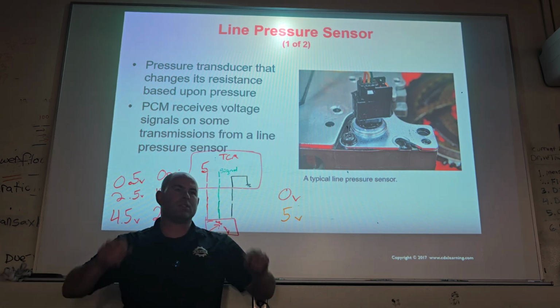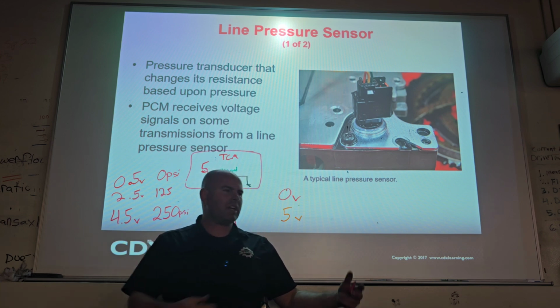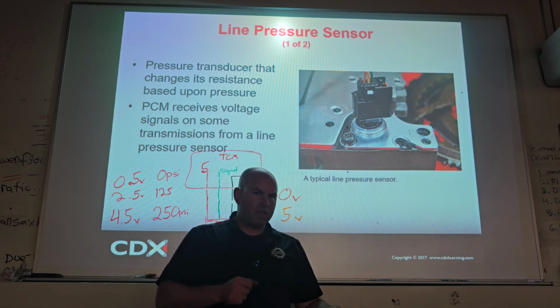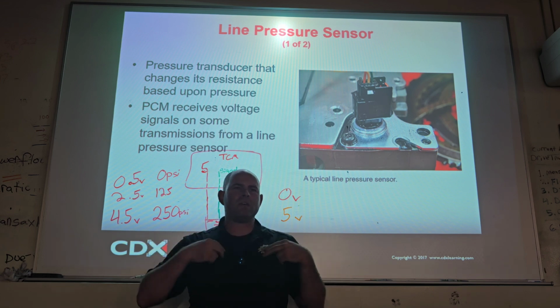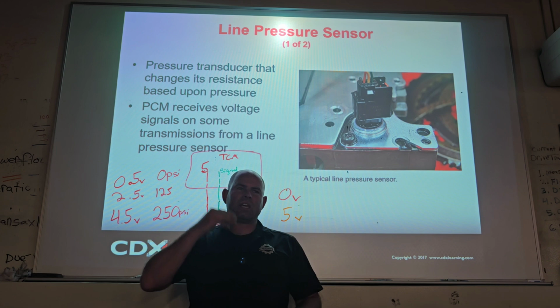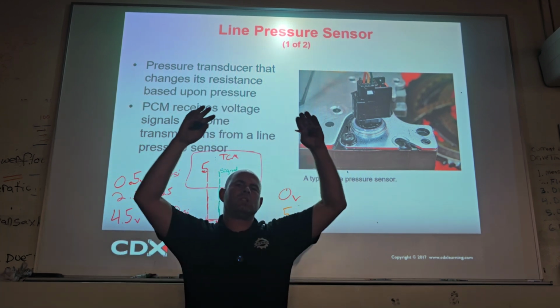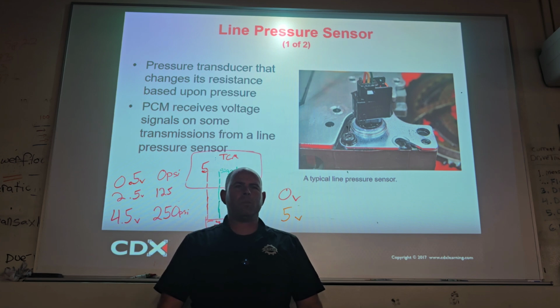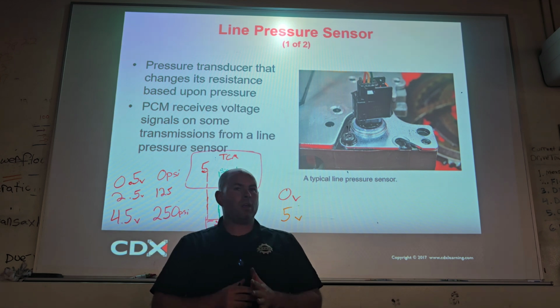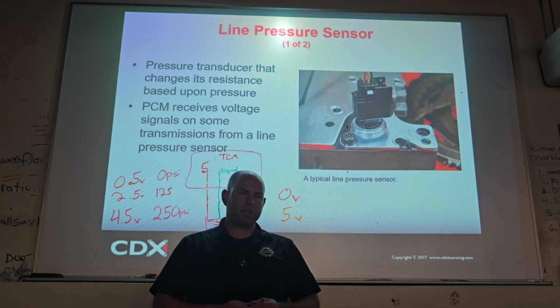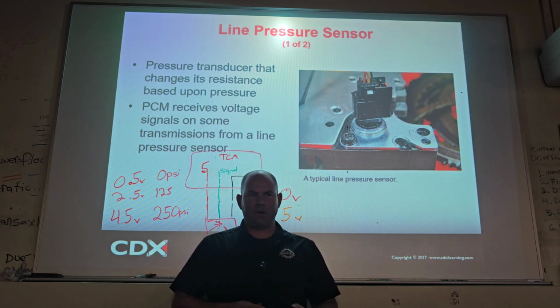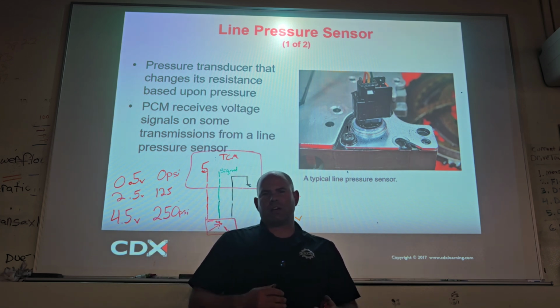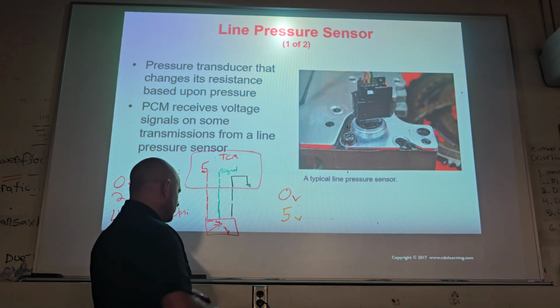If you get to that point, stop. Recheck yourself. Recheck your meter. Maybe go to lunch and come back. Maybe talk to the foreman. Because if you are like me when I was brand new, I did quite a few diagnoses. And if you follow the steps, most of the time all those steps end at replace the ECU. You basically rush through and you get to the end, it says replace the ECU. It may very well be, but it may very, very well not be. And that's expensive. And there's more than one occasion where I had to explain, I diagnosed it as an ECU and I replaced the ECU and it didn't fix it. Make sense? And then next thing you know, I find out I missed something, I overlooked something, etc. Make sense? Okay, so slow your roll.